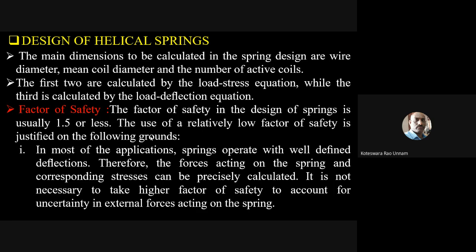In most applications, we can say the uncertainties are less. The springs are operated with well-defined deflections. That means you have prior knowledge of what the deflections of the spring are, so there is no uncertainty. Therefore, the forces acting on the spring and the corresponding stress can be precisely calculated. That's why your factor of safety is low in case of the spring. You can precisely calculate the stresses induced in the spring for a given load, so the necessity of factor of safety is reduced.